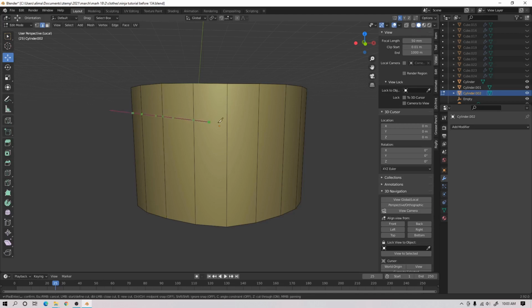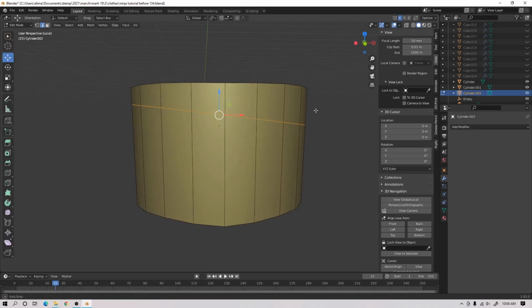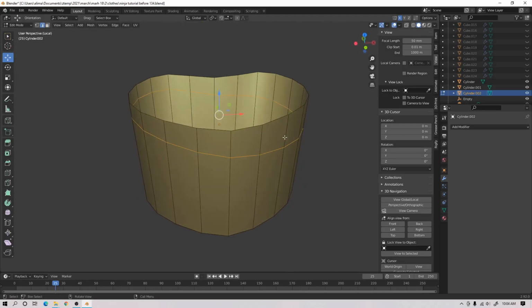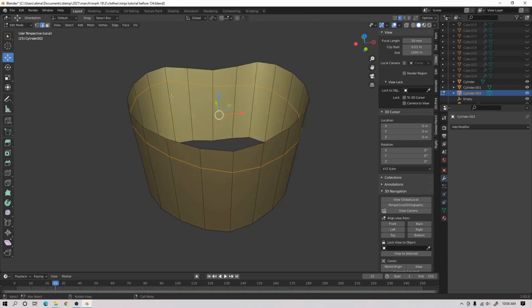So now we'll left click and drag. Then press enter. All right. K, Z, left click and drag, left click, then enter. There we go. Excellent. And what I was checking was that we cut here as well as there. Normally, if you didn't press Z, you would see just this. When we went to see here, you wouldn't see a cut there.